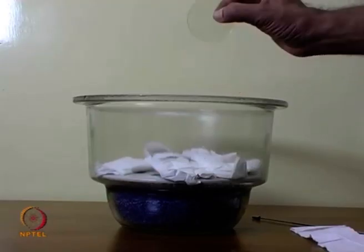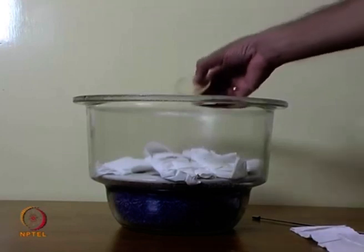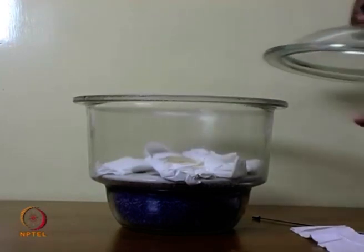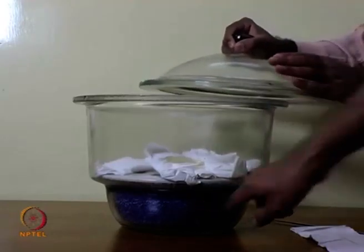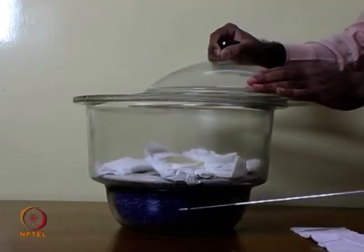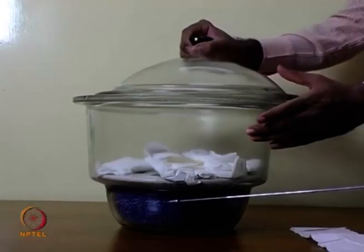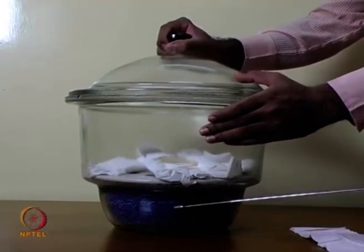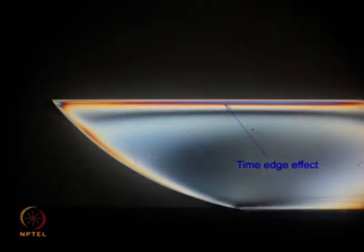So, hold the model only like this, keep it in a desiccator and put it with silica gel, and periodically monitor that the silica gel is in good condition, and this is very important. And if you do not follow these practices, you will see formation of spurious fringes at the edges, which will spoil the model for future use.